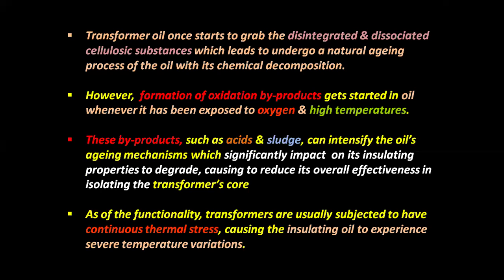These byproducts, such as acids and sludge, can intensify the oil's aging mechanisms, which significantly degrades its insulating properties, reducing its overall effectiveness in insulating the transformer's core.